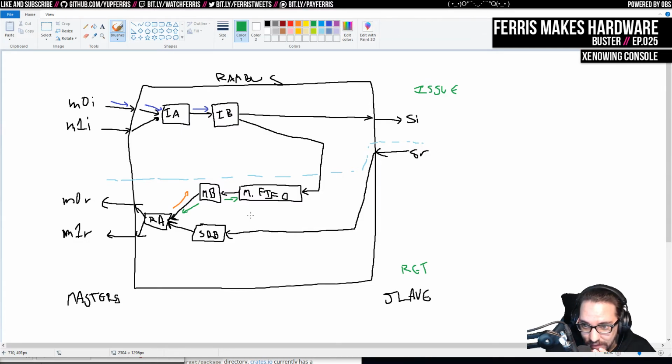Man, you guys, we might actually need a FIFO here. Because then this won't latch the data until the next cycle. So let's say again, this had some data and this had some data. And so then this got read here and this got read here. And let's say on the previous cycle, we issued some more data. So this has a thing in it, and then this does this. So on that same cycle, this can issue a read to this FIFO.